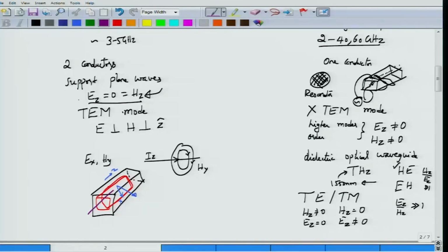So a central conductor must be there which is carrying a current, so that the magnetic field lines can actually form a loop properly. But this is a waveguide, it has only one conductor, so there is no second conductor here. The moment you introduce a second conductor, these are not the traditional waveguides. Because of the absence of a central conductor, there is no way that you can actually have a magnetic field loop around in any region in between the waveguides.